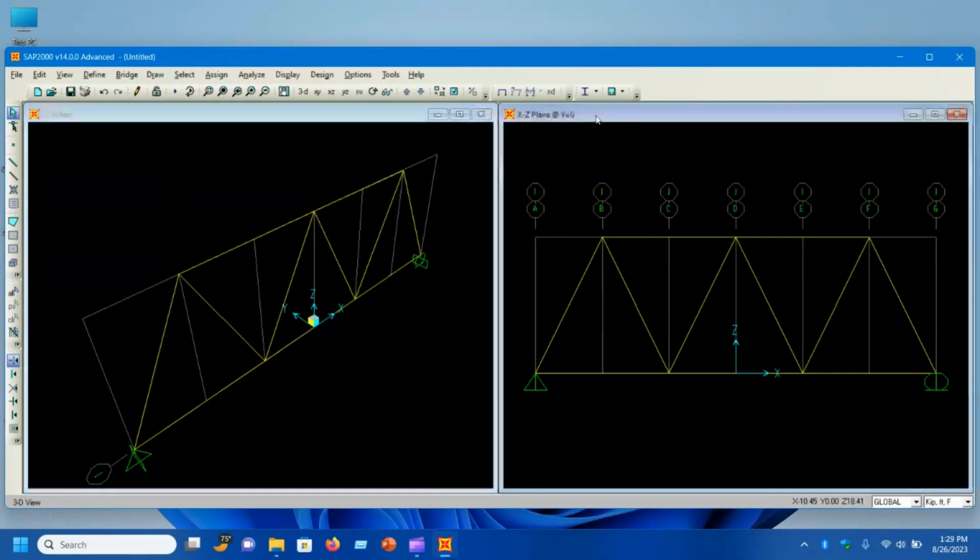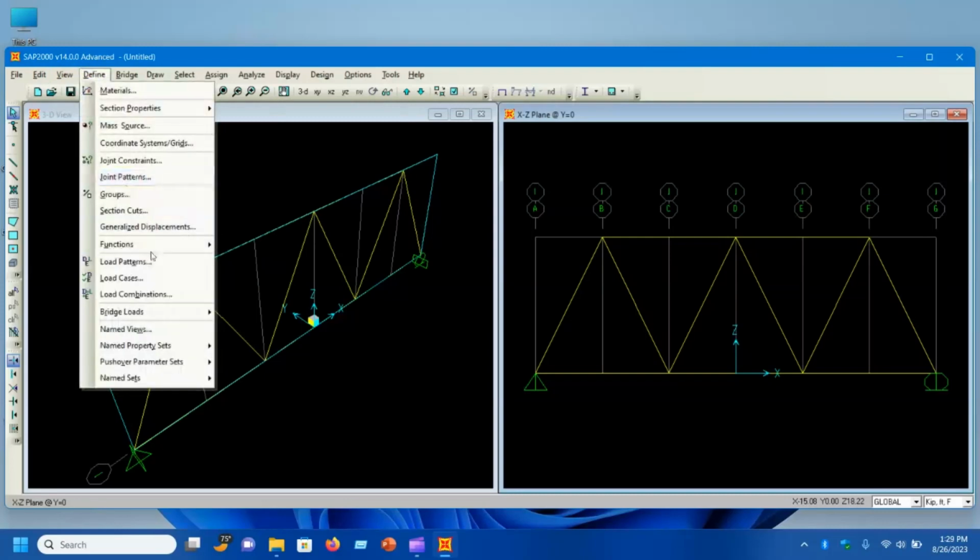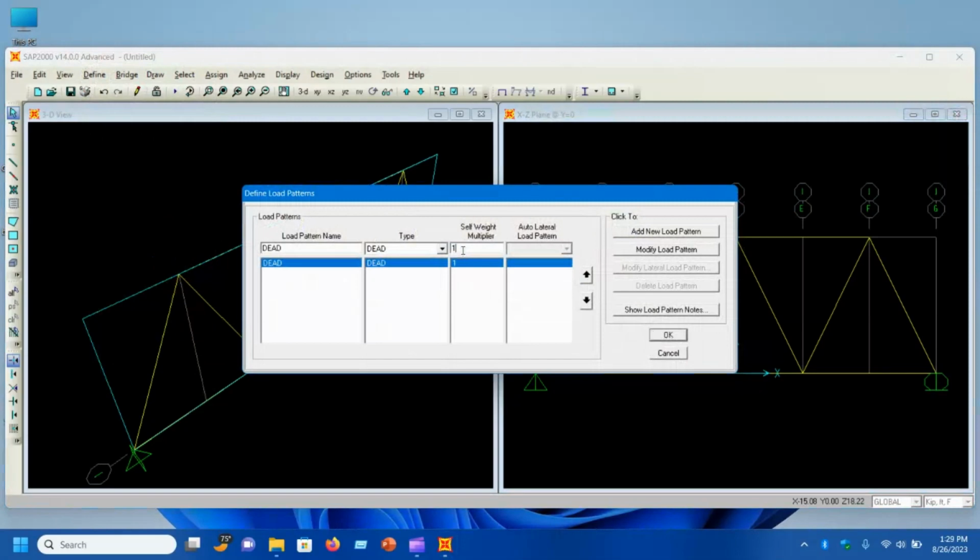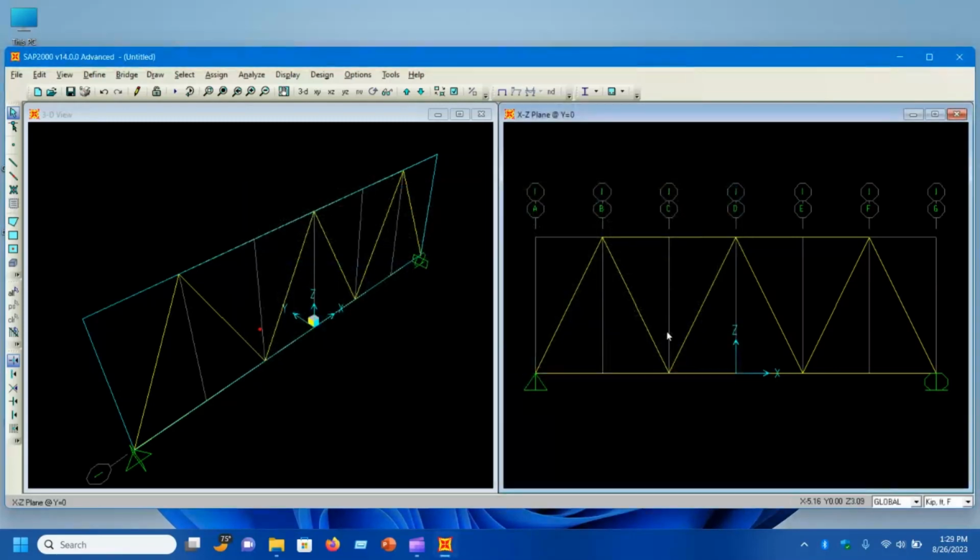This is the model. Now just to compare with the structural analysis concepts, this is just a statically determinate truss, right? It is not indeterminate, and in SAP, since it accounts for the self weight, here I will make the self weight 0, so that it matches the results of your structural analysis concepts when you learn to analyze the truss in structural analysis 1, right? So this is your simple truss.